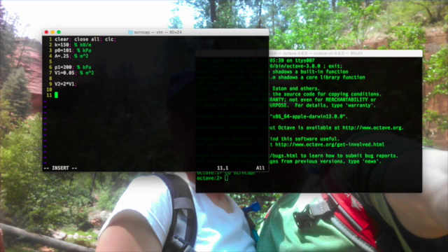The next thing that we've got to do here is solve for the mass of the piston. So the mass of the piston here, P1 minus P naught times A divided by g. Now, this is when it can really pay to look at the units. Our pressures here are going to be in terms of not pascals, but kilopascals.